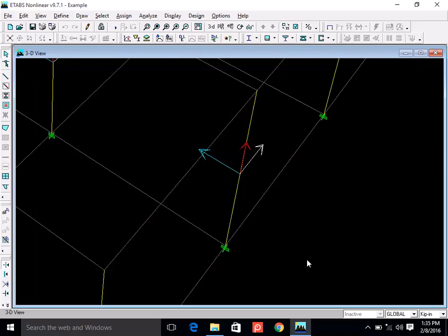Although this is not a perfect example, this is a masonry column. Masonry columns do not have bending moment because that support is either a hinge or a roller. I'm talking about a frame, a concrete frame. So remember this thing, that corner columns have biaxial bending.